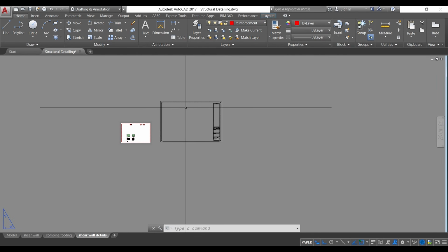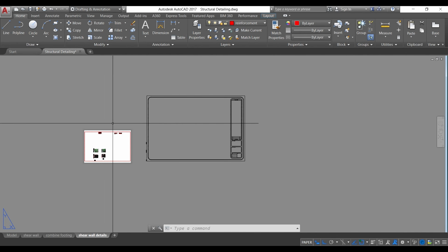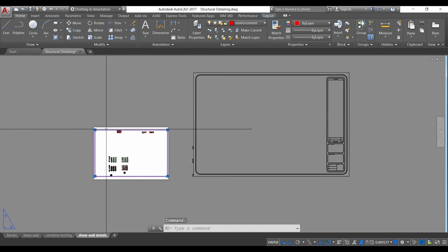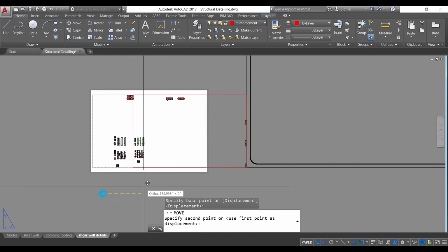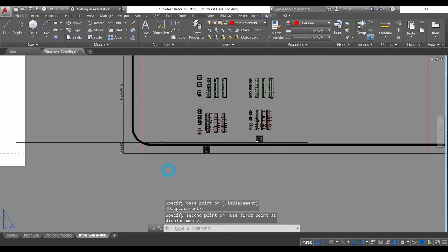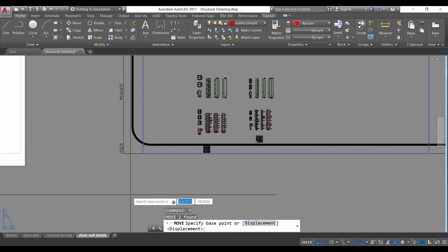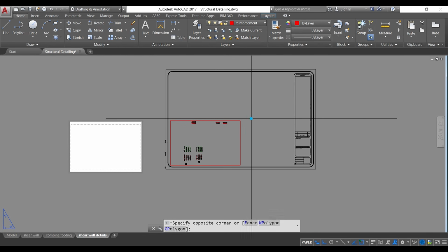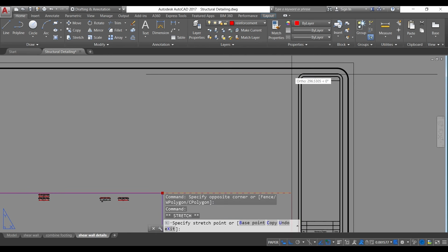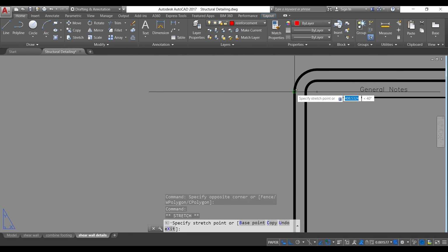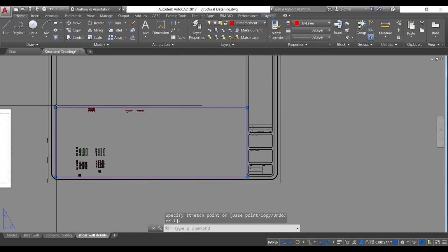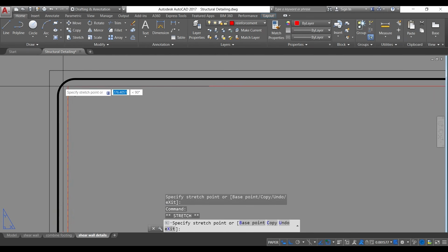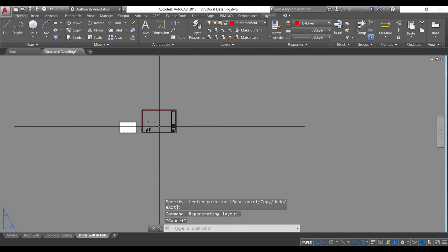The next thing I'm going to show you is how to create a viewport. So this is the viewport that we created, but because you didn't select a location, it was just plotted here. A viewport can be moved anyhow. Like this, I move a viewport inside this place. So you can easily draw a viewport anywhere you want. It's your choice. Then you can also have viewports like this. So this is my viewport.